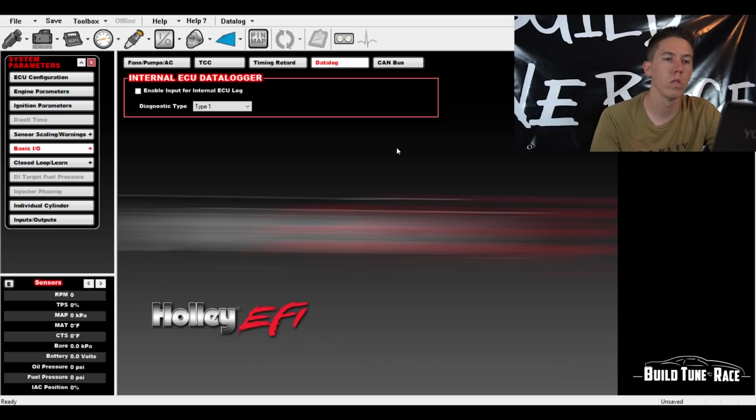Actually, I've done it where I've turned it on with the trans brake, but then you don't get any burnout or anything like that. So I've changed it to where it's a normal data log triggered at 25 frames per second. You can set it for 60 seconds, 3 hours, 10 seconds, whatever you want. I do 60 seconds. I figure that's enough time to get through the burnout. If there's any sort of slowdown or whatever there, it'll go past that.